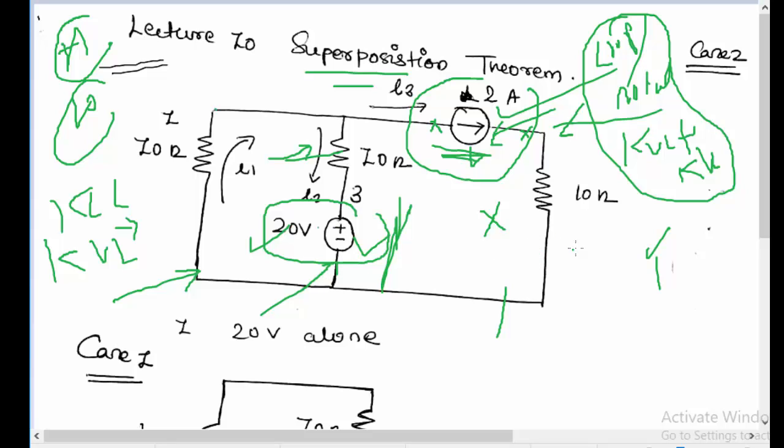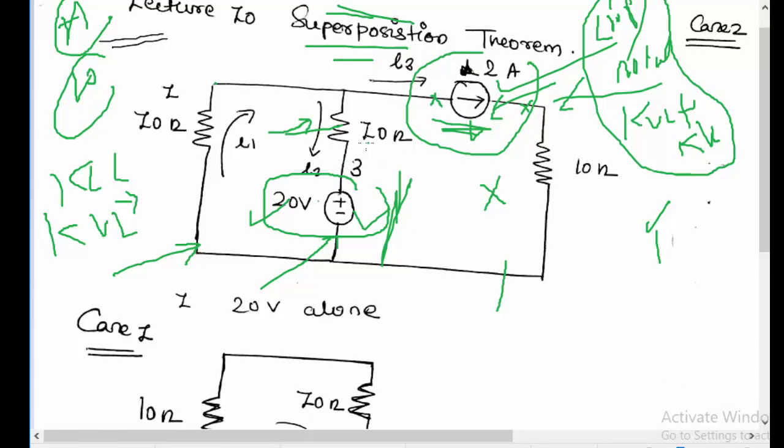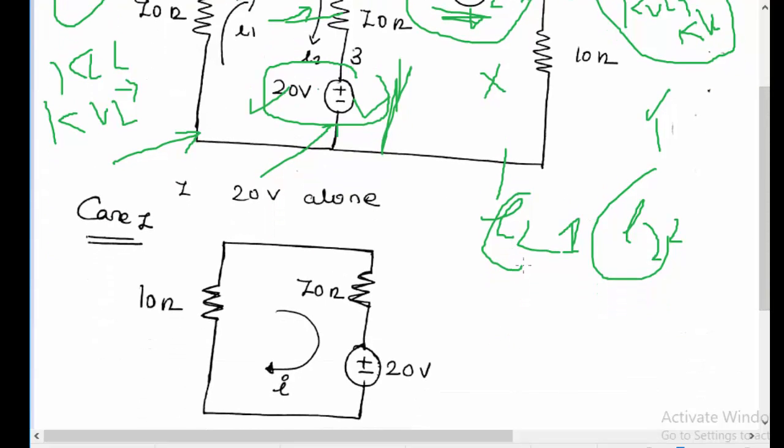So the solution to the circuit can become simpler. That's one of the reasons why you might want to apply the superposition theorem to a circuit. And again, the current I2 which you will find by considering the first active element, and I2 by considering the second active element, will be the two currents which you will be finding, and we will see as we solve them. The current I2 will be the summation of both of these.